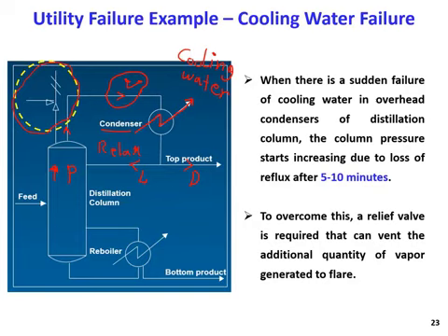Usually, if you don't have cooling water, the pressure starts to increase after 5 to 10 minutes that the cooling water is cut. Then we will have to adjust this valve to take action to purge this vapor. So that's another example of using a pressure relief valve.